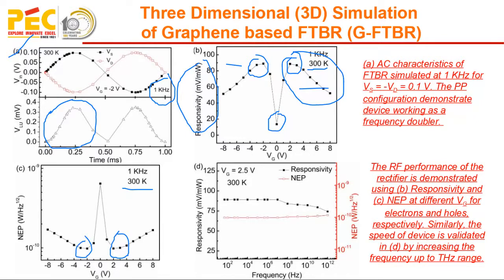Similarly, the responsivity and the noise equivalent power have been measured for different frequencies in figure D, for Vg equal to 2.5 volt at 300 K. So the given characteristic shows that the device works well up to terahertz frequency.